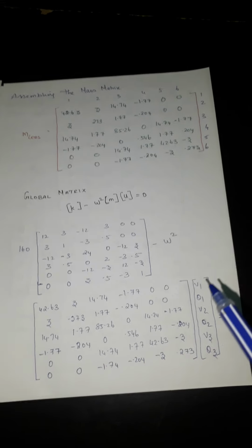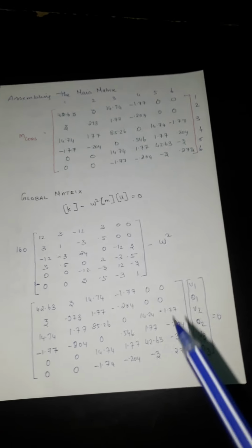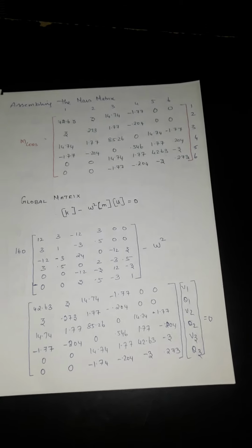Here v1 theta won't be 0, v3 theta will be 0, only v2 theta, because both ends are hinged, there is no displacement at all. So fixed, no displacements, and rotations are 0, both ends are fixed. So this is what I get. Here this is the equation I have substituted, and 0 0 0 0 0.